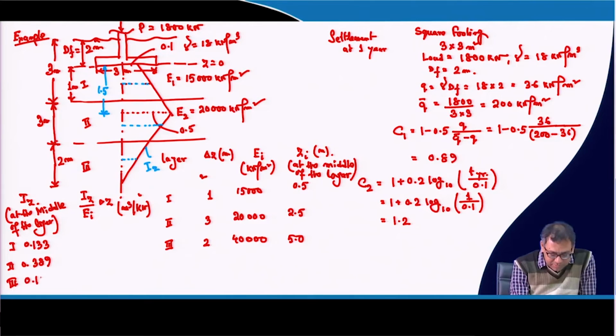Okay. So, basically you can determine it just from similar triangles. You know how to do the linear interpolation: you take this lower triangle, and then you get the Iz value corresponding to these dotted blue lines by linear interpolation. That is the Iz value for the second layer, and this is the Iz value for the third layer. Then we will add them, and the addition gives 8.87 into 10 to the power minus 6.